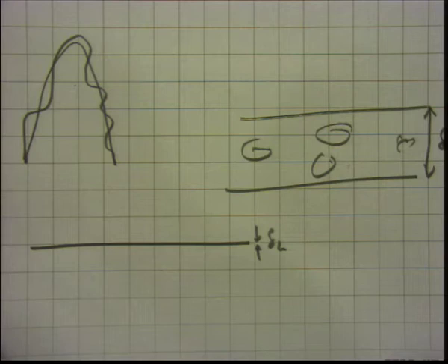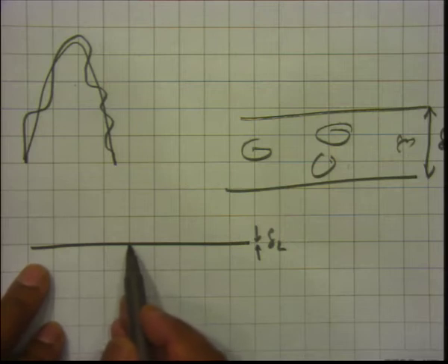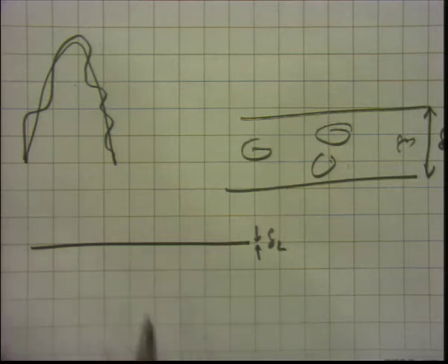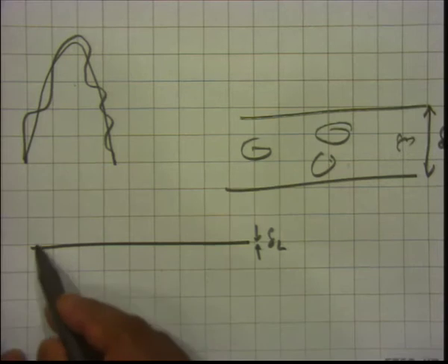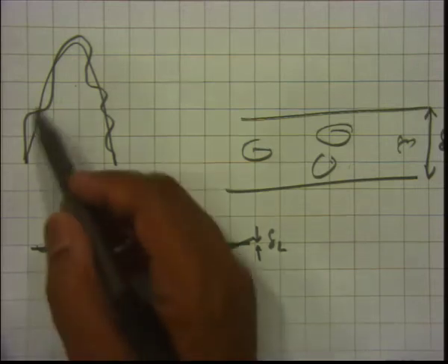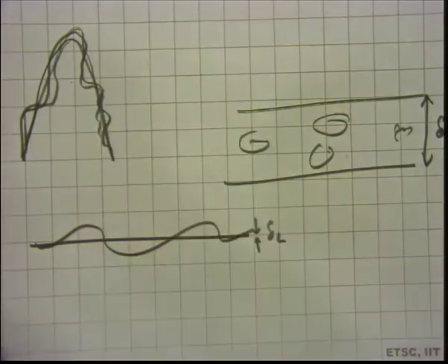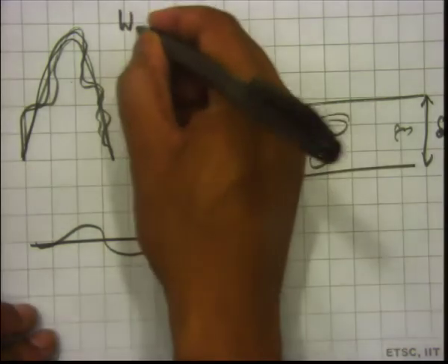Okay. The fluctuations and the vorticity in the turbulent flow field cannot actually change anything very significantly within the thickness of the flame, because the turbulent processes are too large. But it can actually change this by twisting it. It can do that in a turbulent flow field. So, that is why you get something like this, a laminar flame which has been twisted around by turbulence. So, this is in the wrinkled reaction sheet regime.